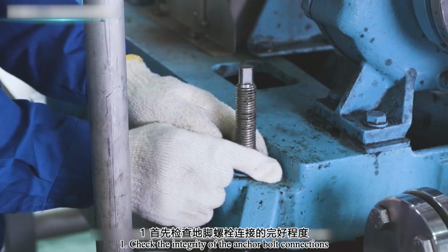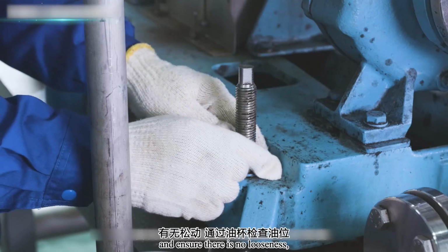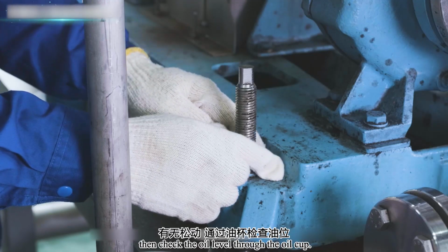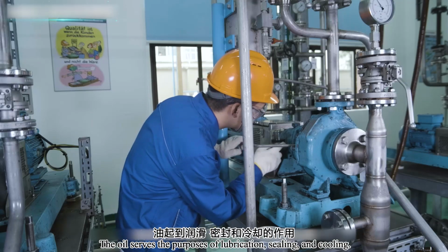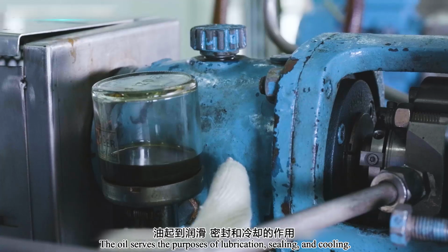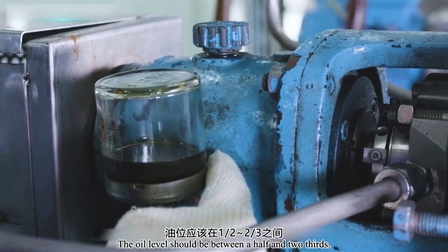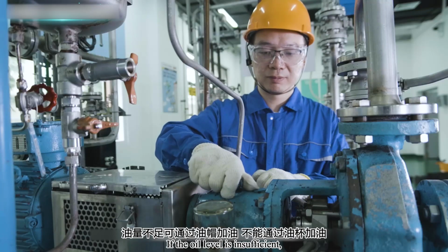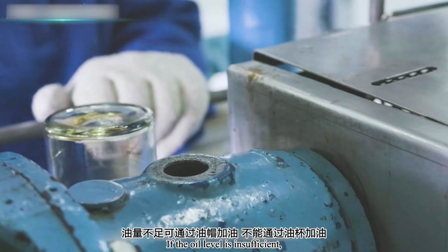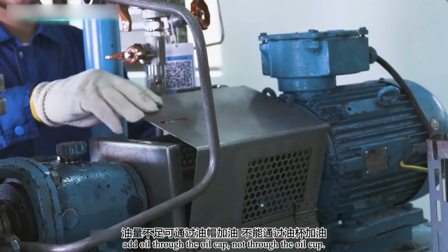First, check the integrity of the anchor bolt connections and ensure there is no looseness. Then check the oil level through the oil cap. The oil serves the purposes of lubrication, sealing, and cooling. The oil level should be between 1/2 and 2/3. If the oil level is insufficient, add oil through the oil cap, not through the oil cup.